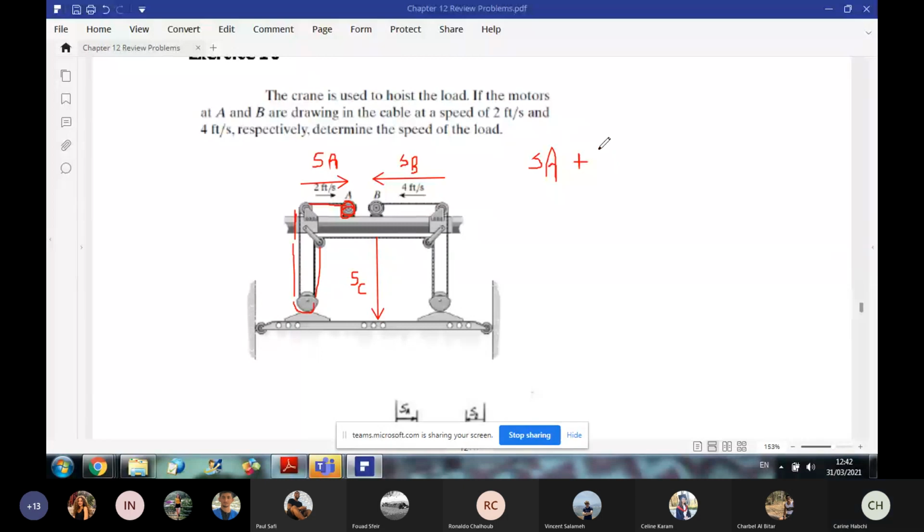So now for pulley D, the center of pulley D is attached to the periphery of a moving pulley, so it's not fixed. Then I need a coordinate for D, so I will take S of D. And for pulley C, the center of pulley C is attached to a block that is moving, so the block and the center of C will move together. So I just need to take S of C like this.